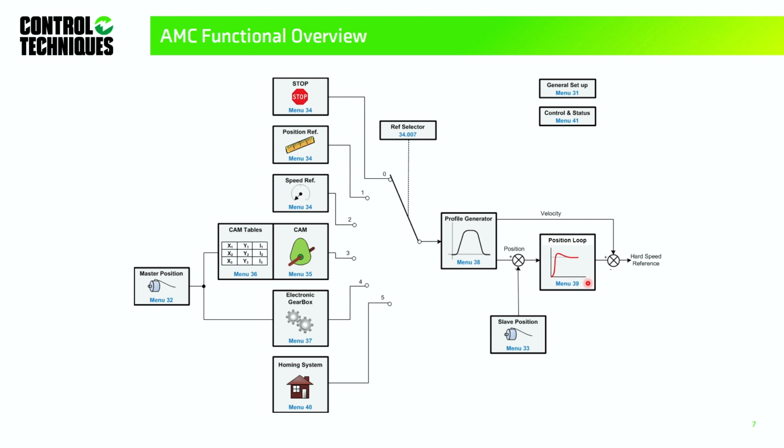So this is a full-on servo now, in the sense that the base drive itself holds the current loop in menu 4. The speed loop is also held in the base drive itself in menu 3, but the position loop is in menu 39. So we have our proportional gain term here to reduce or eliminate position error.